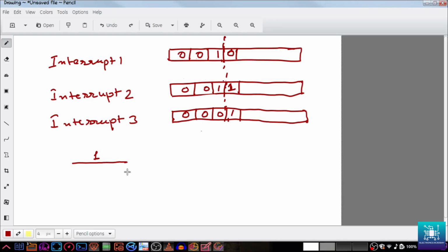Interrupt 1 will keep executing until it completes, and then 2 will start, because its sub priority gives it a lower priority than interrupt 1. Interrupt 3, of course, has a higher priority because it is 0.